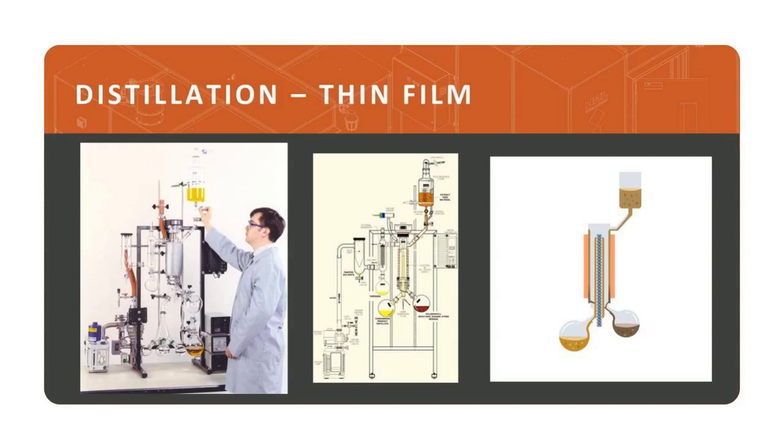That's chilled to condense those evaporated compounds back onto that core piece, and they then drip down to a separate flask at the bottom, apart from where the crude oil and the undesirables drip. So again, same process, just a little bit more efficient because we have that mechanical assistance to spread this initial solution into a much thinner sheet, allowing for increased evaporation and increasing your efficiency.